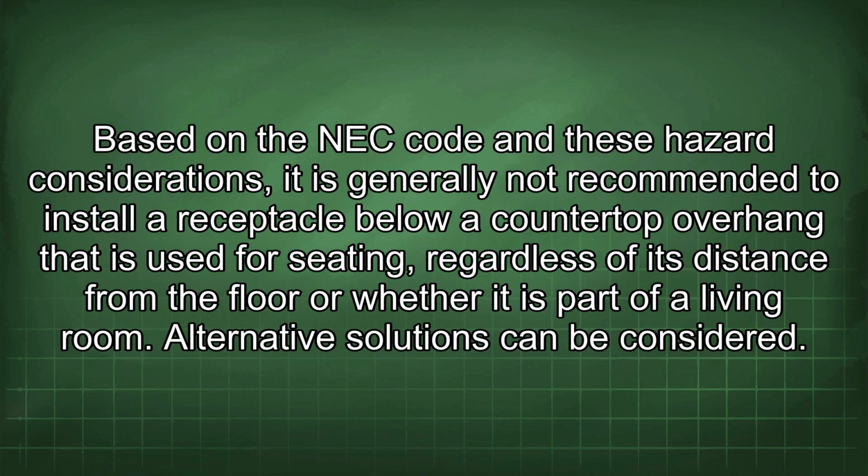Based on the NEC code and these hazard considerations, it is generally not recommended to install a receptacle below a countertop overhang that is used for seating, regardless of its distance from the floor or whether it is part of a living room. Alternative solutions can be considered.